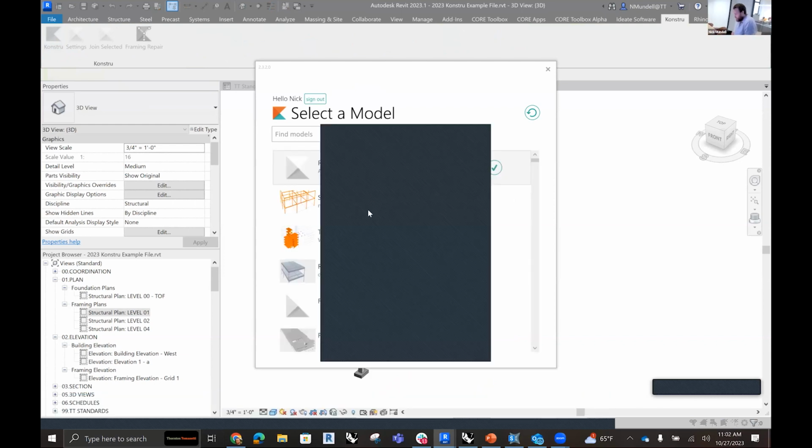Can you go back from repair? You could undo. If you really needed to, in Revit, it's a process we applied. So there is the possibility of undoing the changes that framing repair made to Revit. But that's about it. The key here is that the change we made was with the analytical model, not the physical. Undo is possible. Good suggestion from Jason there. If you're really concerned, you could save a copy of the Revit model before making the changes.